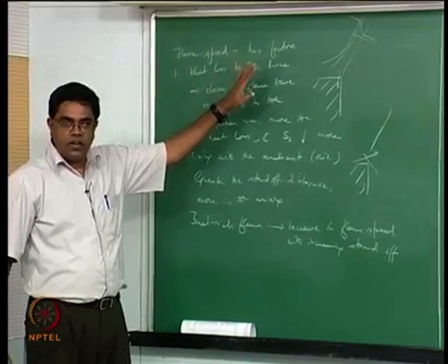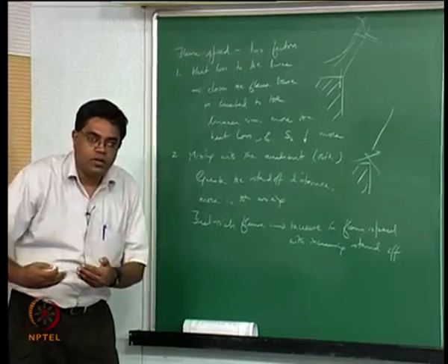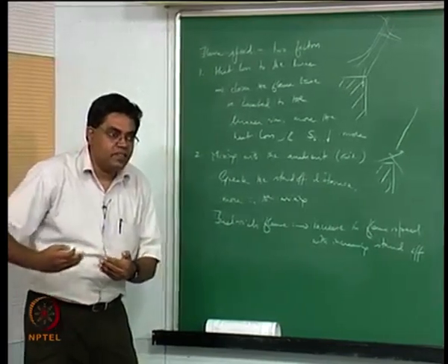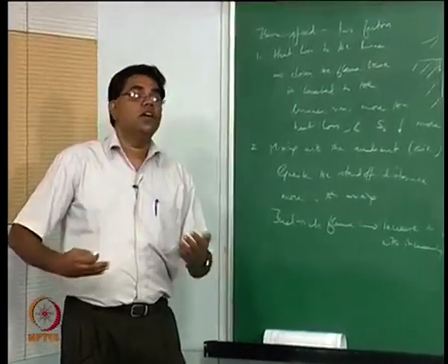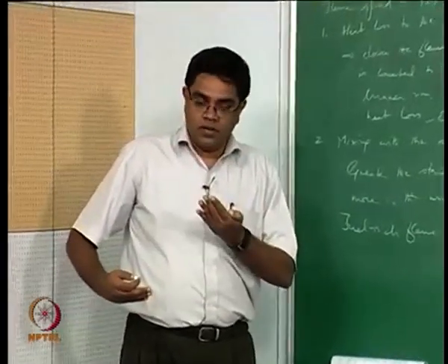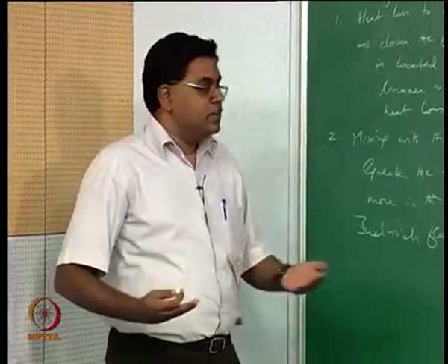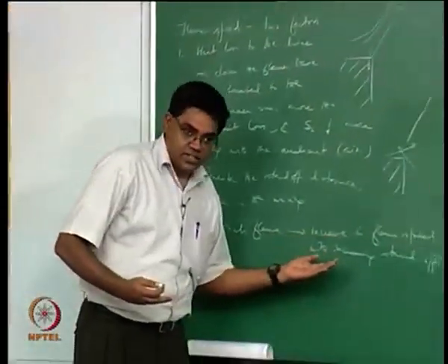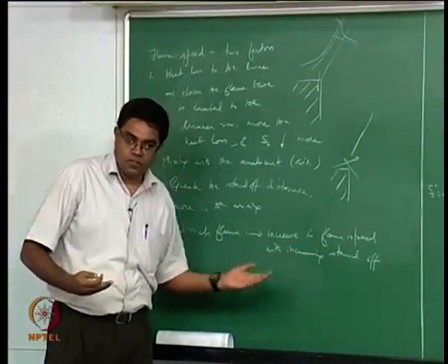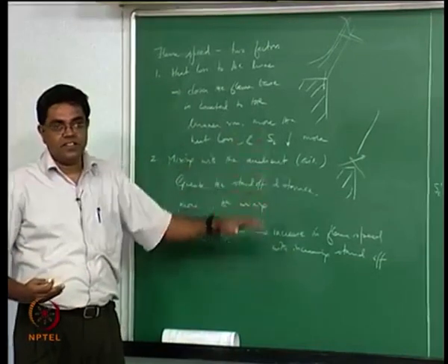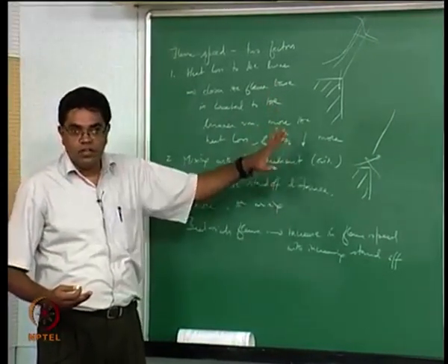In the case of the heat loss, what we understood was the closer the flame is to the burner, the lesser is its flame speed, or conversely, the farther it is from the burner, it's going to have a higher flame speed because of less heat loss. This is exactly what we are saying here. An increase in the flame standoff means an increase in the flame speed because it's fuel rich. So in this case this is a little bit more complicated, and we will talk about this later on.